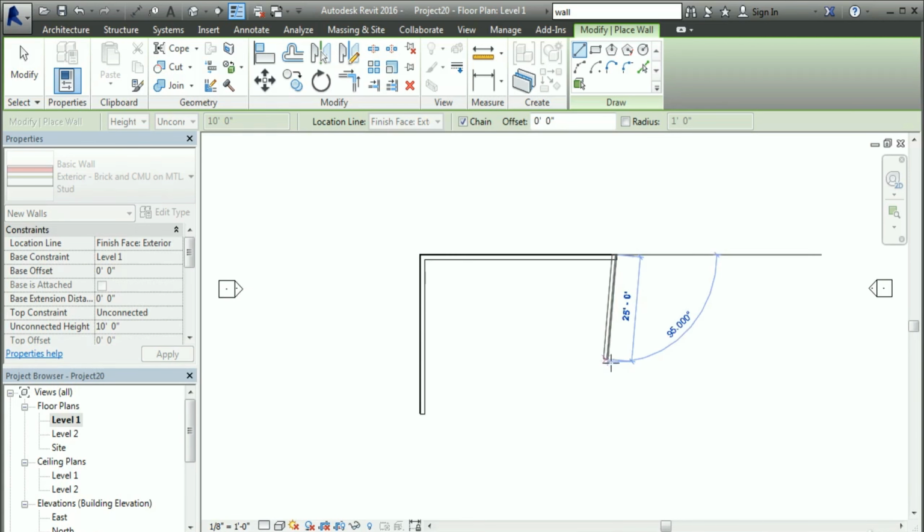Now I'm going to drag my mouse down approximately the length of the first wall, and as soon as I get to that same length, this little tracking line appears indicating a perfect alignment with the first wall. So Revit's very clever. It will often show you little alignment lines or smart alignments indicating when things are in line with other things that you probably want to align.